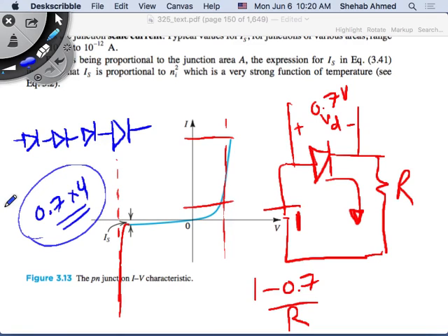If, let's say, you don't care, because there's power loss associated with this, of course. Each one of these has a power loss, V forward. And that's coming from a power source, right? In this case, it has to come from more. If I want to create a voltage regulator for 2.8 volts, I have to put something greater than 4 times 0.7. So that's how they regulate. I can put maybe 4 volts here.